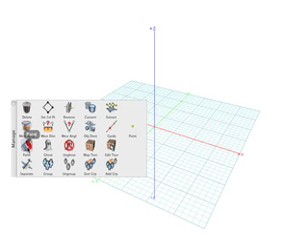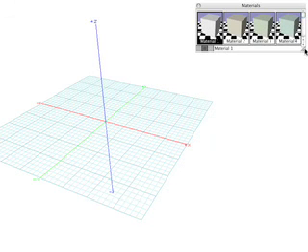The Paint tool, which is used to assign a new material to an object or the face of an object. The Map Texture tool, which allows you to assign a different mapping type to an object or face. And the Edit Texture tool, which is used to interactively adjust the orientation, size, and position of the texture live in the modeling window. We'll begin by looking at how a material is assigned to an object.